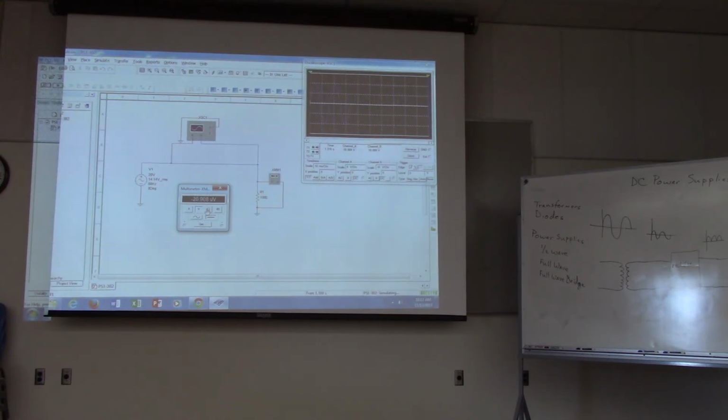Microvolts. So we're talking about 15 or 20 millionths of a volt, right? Very, very small signal. So why would that, I mean, we can see that there's a pretty big signal on the screen here. Why would we be seeing almost no signal on our meter? It's set to DC. Yeah, it's set to DC.